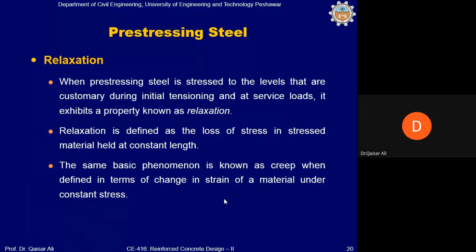So it is important for the concrete member to remain in a pre-compression state of stress, and for this it is necessary that steel shall be in a stretched position, and any recovery or regain in the length of the steel will cause a pre-stress loss.